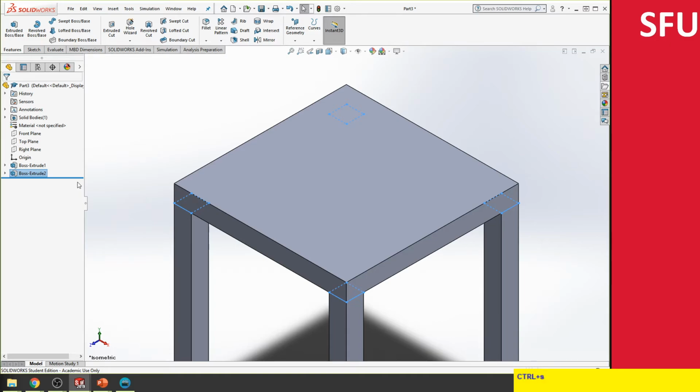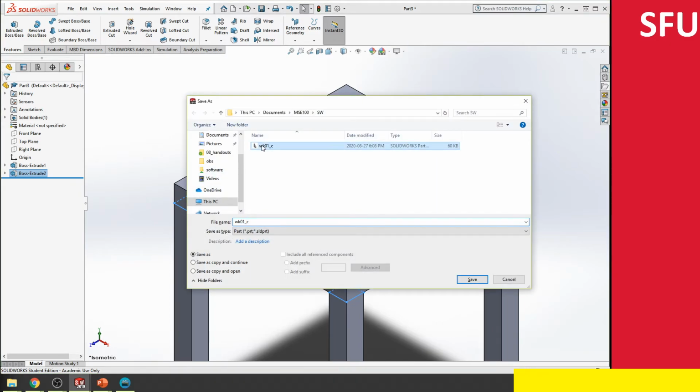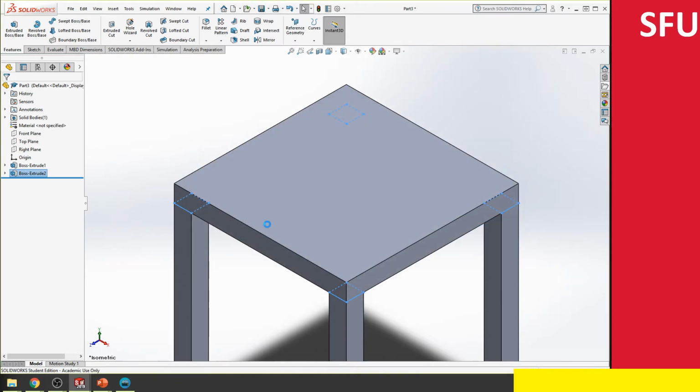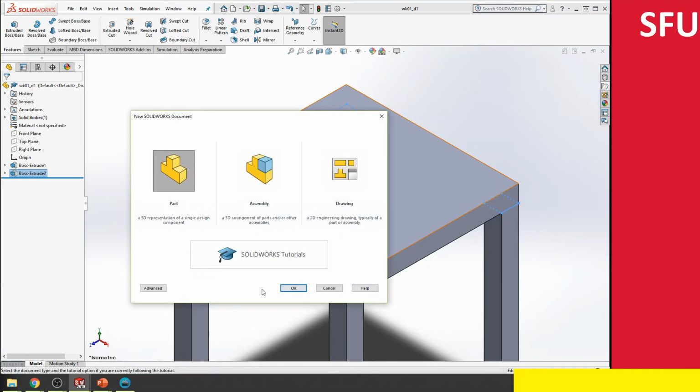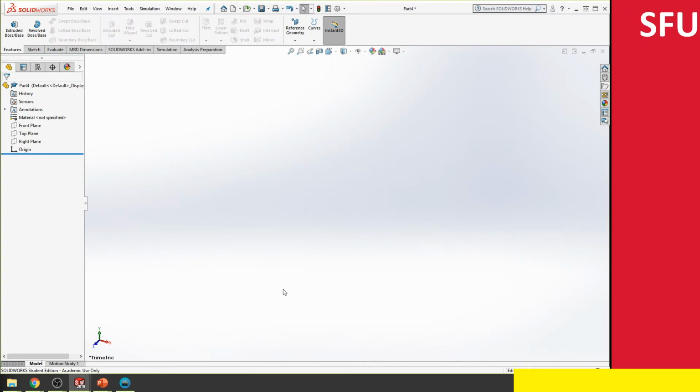So let's save this. Then maybe P1, do one more new part. And then we're going to create the table by sketching on the, you can do it right on the front plane because the symmetry doesn't really matter. So let's do it on the front plane.